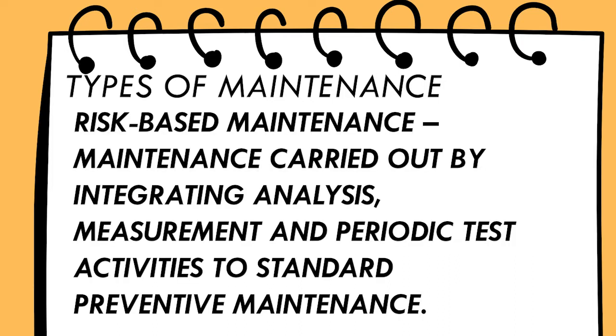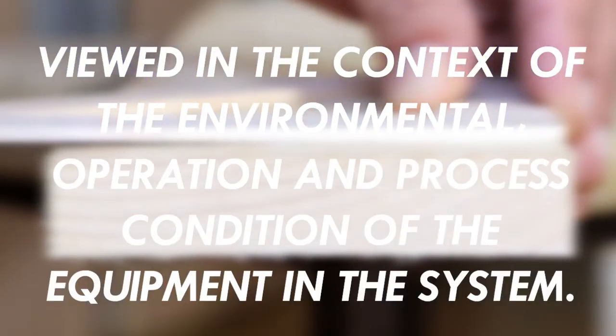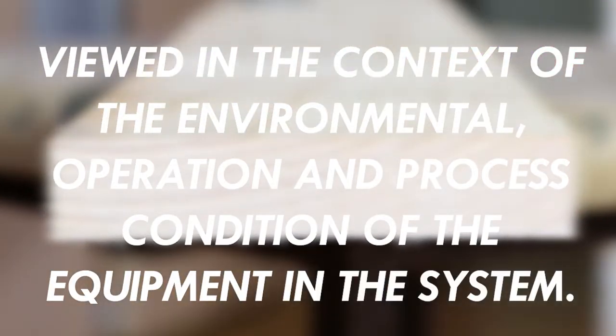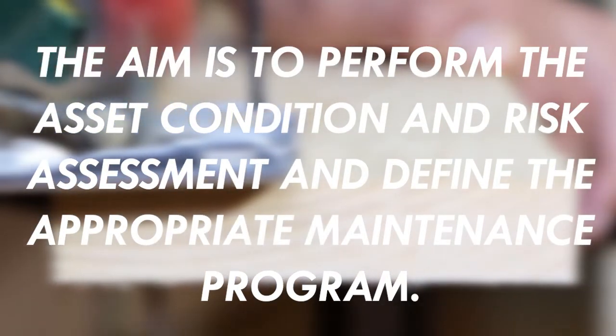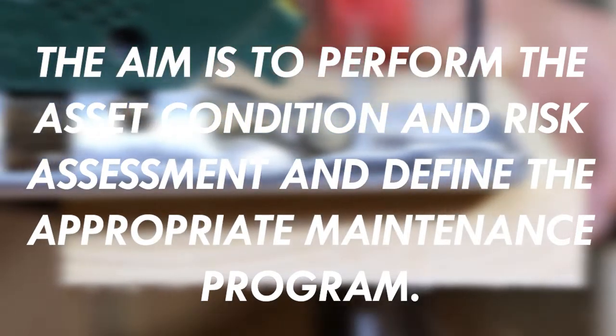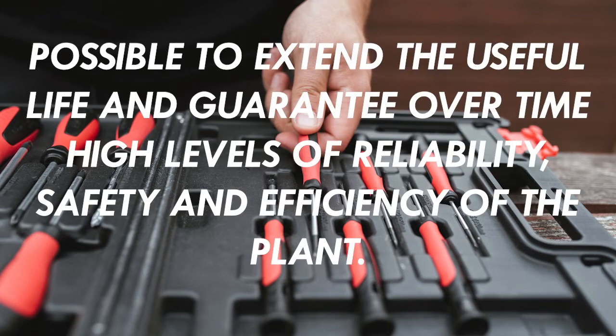Next is the risk-based maintenance. Maintenance carried out by integrating analysis, measurement, and periodic test activities to standard preventive maintenance. The gathered information is viewed in the context of the environmental, operation, and process condition of the equipment in the system. The aim is to perform the asset condition and risk assessment and define the appropriate maintenance program. All equipment displaying abnormal values is refurbished or replaced. In this way, it is possible to extend the useful life and guarantee over time high levels of reliability, safety, and efficiency of the plant.